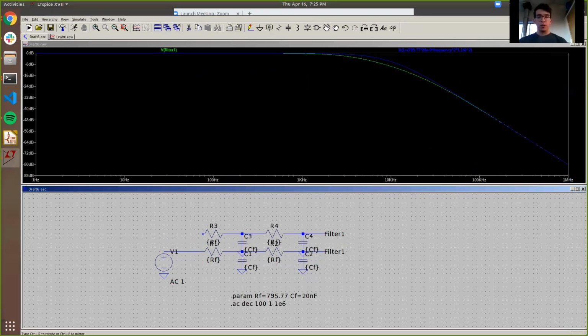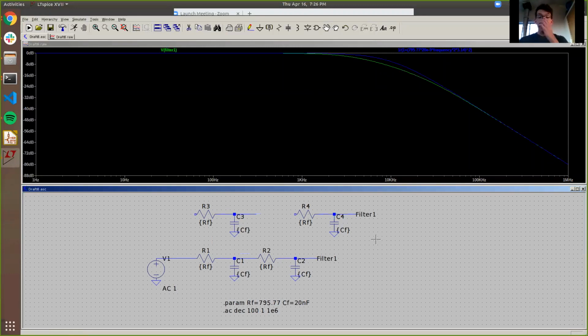Cool. So copy the filter, pull it up, and then we're going to make a bit of space for the op amp. So you want to use the move little hand that's open, kind of like Spock. Sweet. So you want to move, select the R and the C, drag those over. Sweet. And now we want to add an op amp.